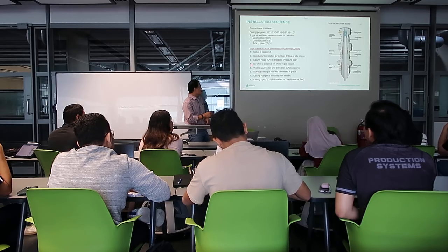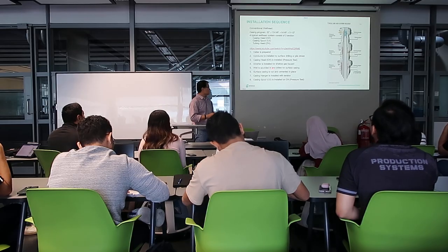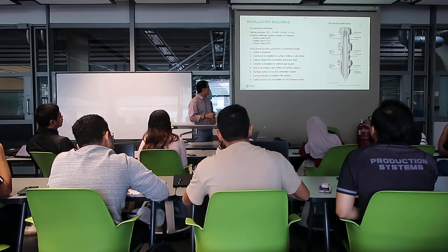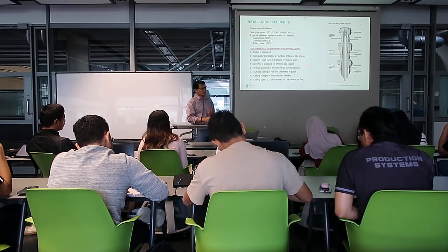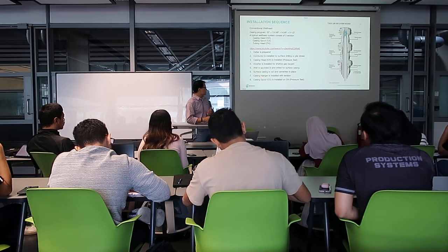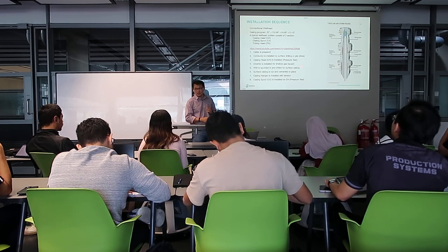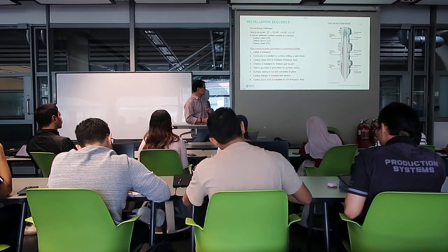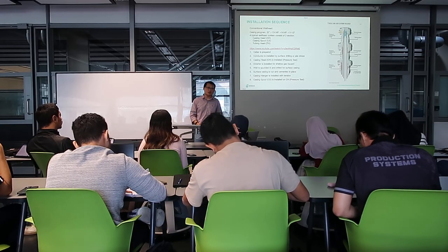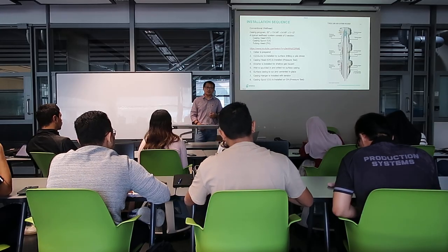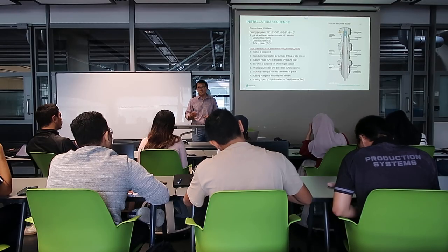So we put the diverter for shallow gas, then we spud the well, drill for surface casing, then we will... screw is installed, then whenever we install the wellhead, we try to test it as soon as possible. Because why?